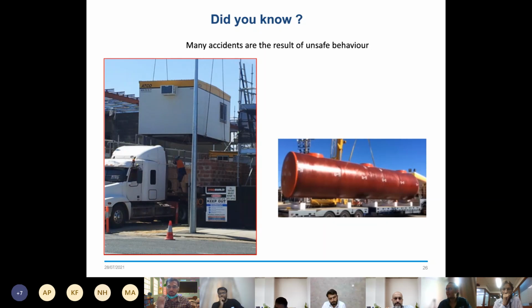So that's why, in our industry and practices now, for all tank installation programs, the tank supplier should provide the sling bag together with the tank. So meaning that on site there is no working at height for them to put the sling bag and hook and then only do the lifting activity. So we already agreed to that. After they hook, they lift up the tank.